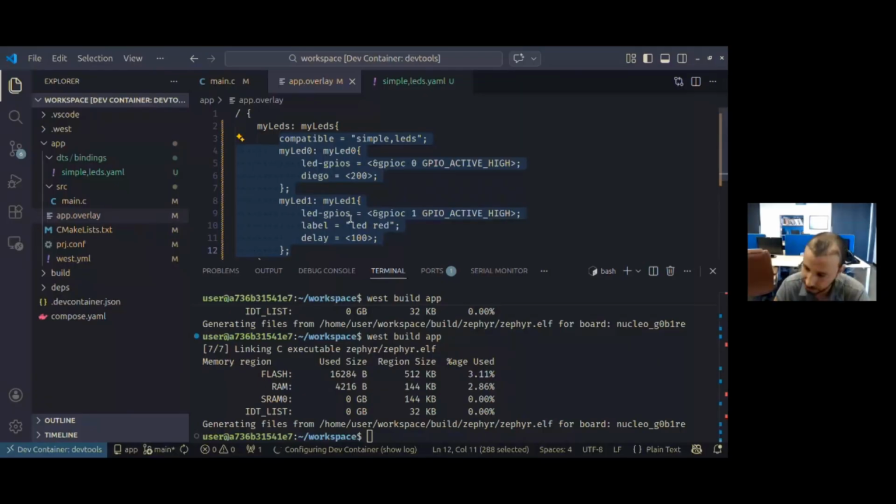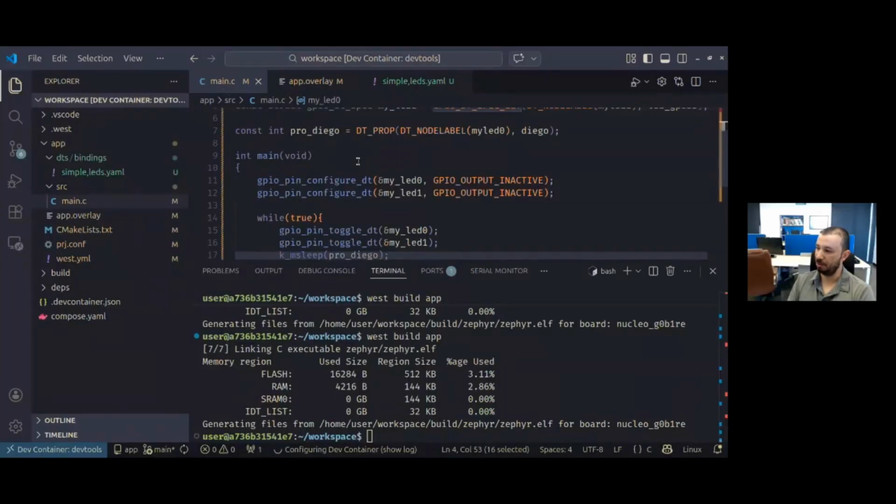It could be internal from the same microcontroller or external, like a memory, like a display, like any kind of sensor. All right. So we should be able to declare the properties in here, like for instance, the UART baud rates, to give an example, pins to control or to read an interrupt from the external sensor, whatever you name it, resolution from the displays, and so on. And we should be able to learn how to extract this information to start using it in our C code.